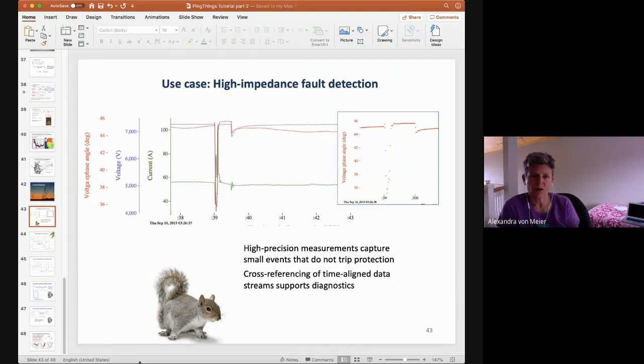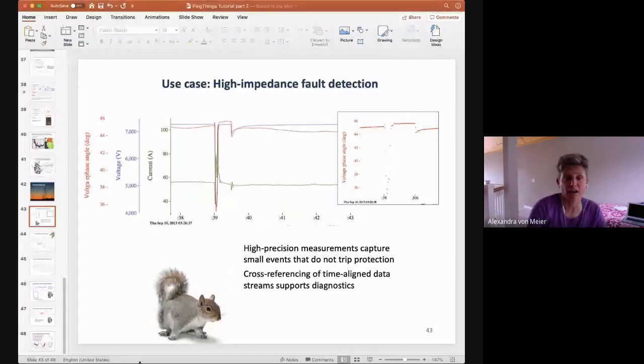So we could show that a high impedance fault, which is not a very respectful way to talk about a dead squirrel, but a high impedance basically does not allow a lot of current to flow, which means that the circuit breakers aren't disconnecting or interrupting this fault. So basically the squirrel is going to cook until it's done and falls to the ground and the voltage recovers.